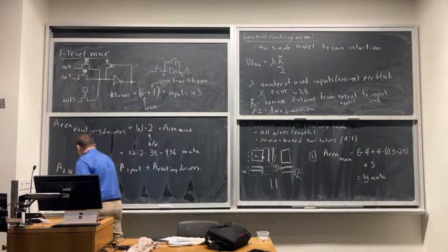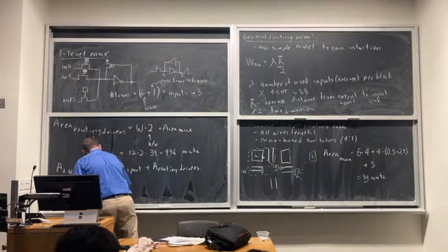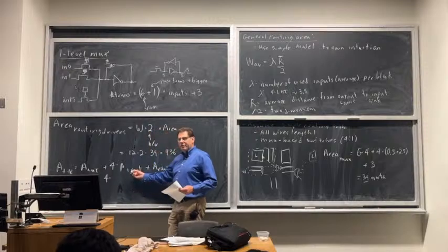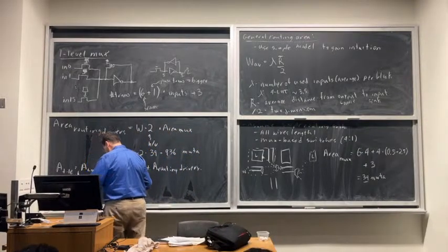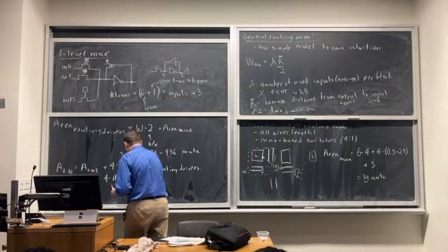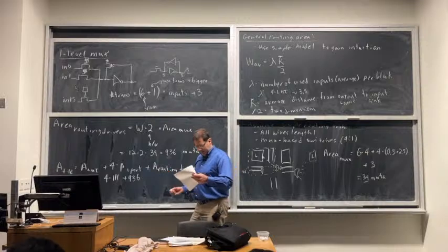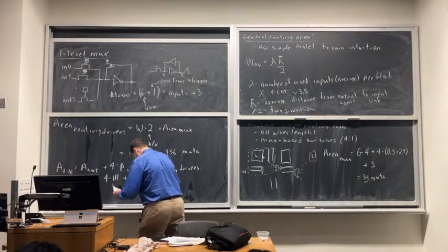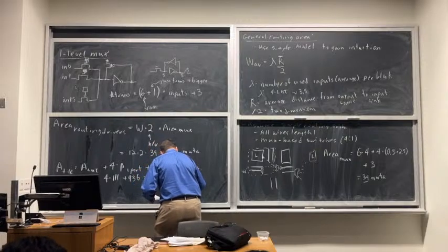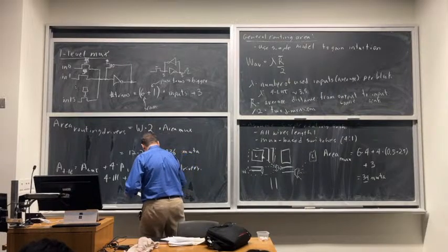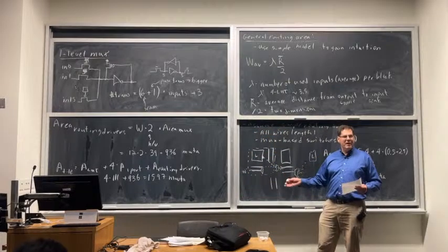Okay, so the LUT we said was 217. Our most area efficient way of building these input ports when they're 16:1 muxes was 111. Just worked out the area of all the routing drivers is 936. If we add it all up, we get 1597. Okay, so this is in minimum transistor areas, but clearly that's a reasonably big number compared to just a gate.